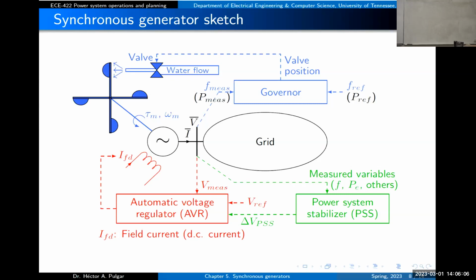So if you're controlling, for example, the mechanical side of the generator, at some point you're going to have oscillations in the machine related to the motion of the generator. And that, by definition, is going to be slower than the dynamics that you expect here, right? So with this power system stabilizer, we're going to try to help control those oscillations that happen at the mechanical time scale with something that can respond faster, which is a loop in the AVR. We're going to close a loop between typically frequency, something related to the mechanical side, and the electrical side by controlling the voltage.